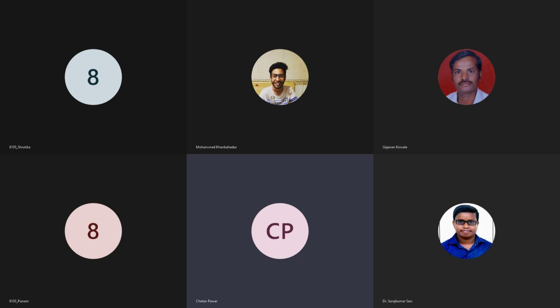And one more thing, please wait. I am showing you. Right, V pulse here. V pulse is nothing but voltage in the form of a pulse. I'm explaining you one by one. Just see how I am doing. See, this is only the test bench. We have created a symbol and we are testing that. This plus symbol indicates the positive voltage and the negative will always be connected to ground. So we will copy this one and put one ground.